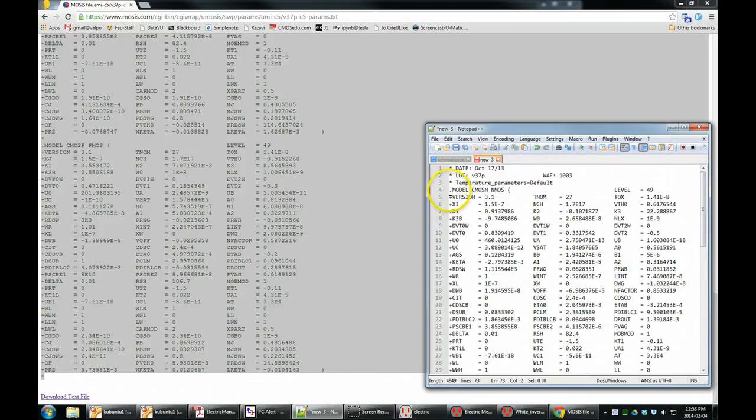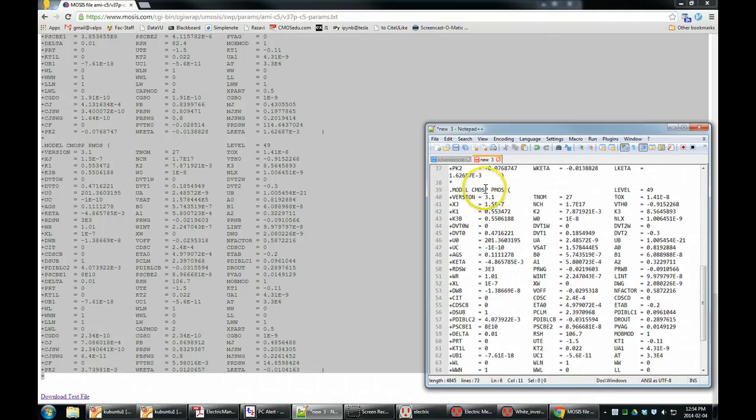There we go. Now this .model is an NMOS transistor, but here they named it CMOS-N. We have two choices here. We can name this model anything we want. However, in Electric, it wants to call an NMOS model an N, just N, and that's the easiest for us, so we'll change the model name here. We'll call that N. Scroll down for the P version. There we go.